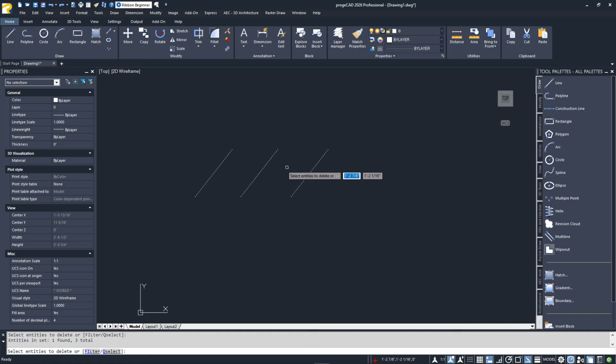An even faster way to toggle between removal and addition modes is with the Shift key instead of the R and A. Press it down during selection addition mode and it will turn it into removal mode. Release the Shift key and it will return to addition mode.